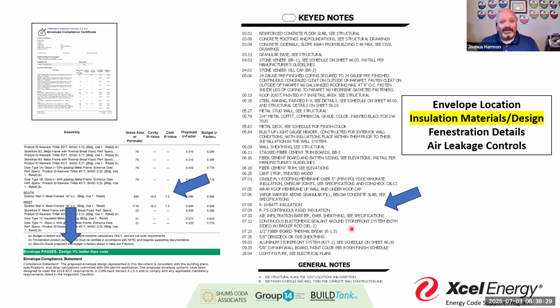Now, I may need to know that inch or 2 inches based on other components and requirements of my design, as far as fasteners or those kinds of things. But from an envelope energy evaluation, I need to know what is going to be that thermal resistance. And so you might get something like we see down here, where it's a 1/2 inch fiberboard thermal break at an R1.23, right? So you can provide both details, just make sure we get our R values. And like I said, a lot of times I see both, where it's 2 inches or 1.5 inches of rigid insulation, R7.5.